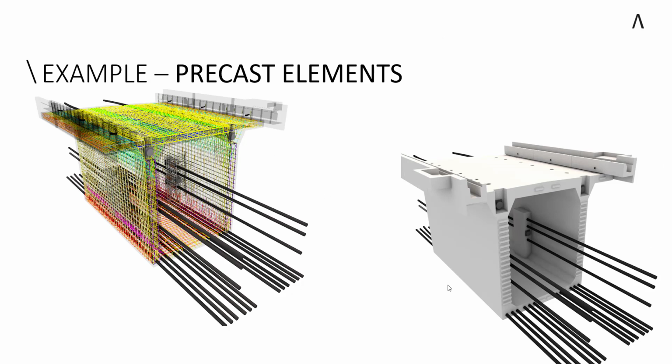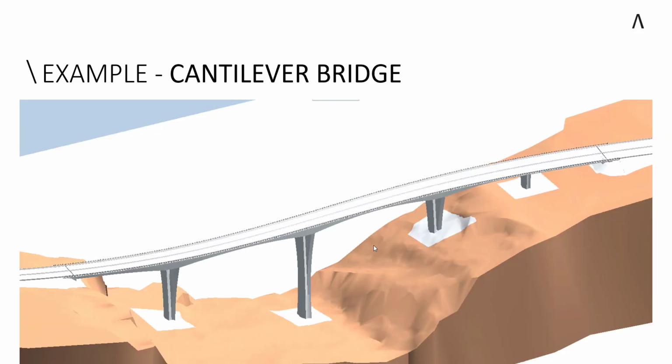Here one of these blocks, and here you can see also on the tendons, which are coming directly from Allplan Bridge, the smart placement of anchor blocks and so on, they are directly placed, so this was easy and smooth going. Also, as the tendons and their location, the whole thing was planned and set in 3D, the reinforcement was also easier to get into its locations. Clashing and so on could have been avoided due to already precise 3D planning. Yeah, very impressive project. Here the next example is a cantilever bridge.